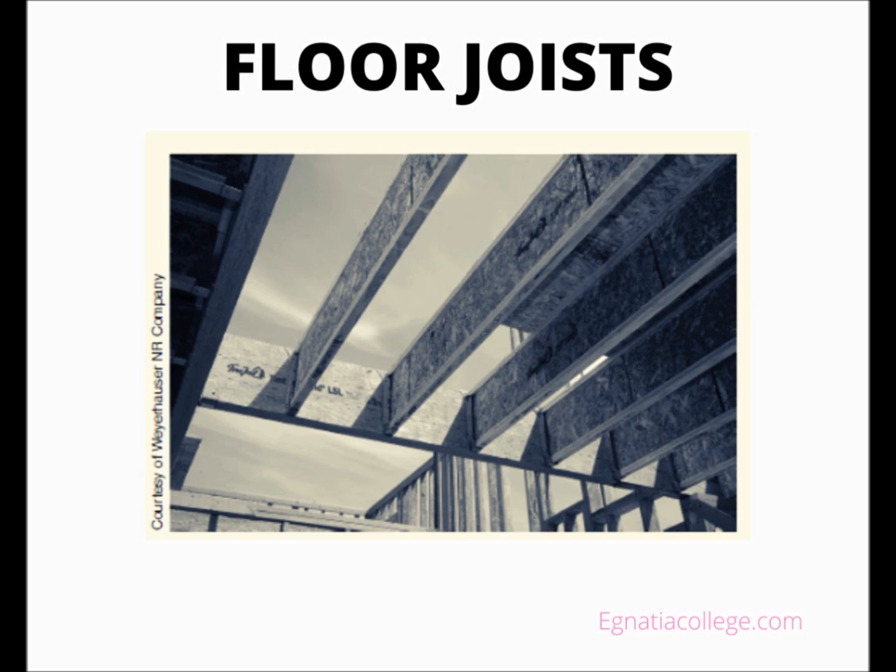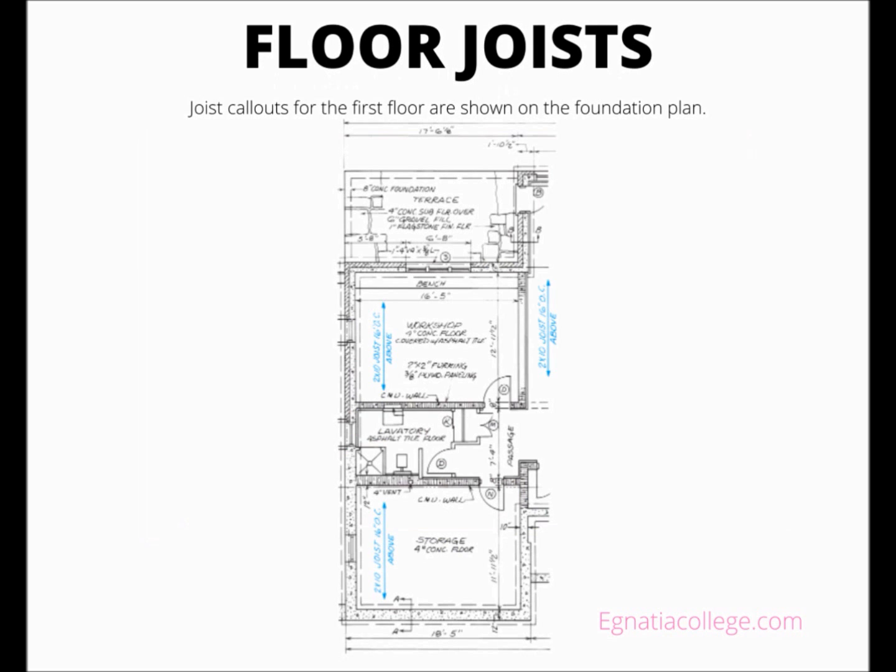I-joists are often called TJIs because the first I-joists, introduced over 40 years ago, were named after the Truss Joist Institute, which developed the first I-joists. Although the materials in each type are different, their use is essentially the same. The joist header in each case is of similar material to the joist. When I-joists are used, the header is typically an engineered rim board that is manufactured to have the same depth as the I-joists.